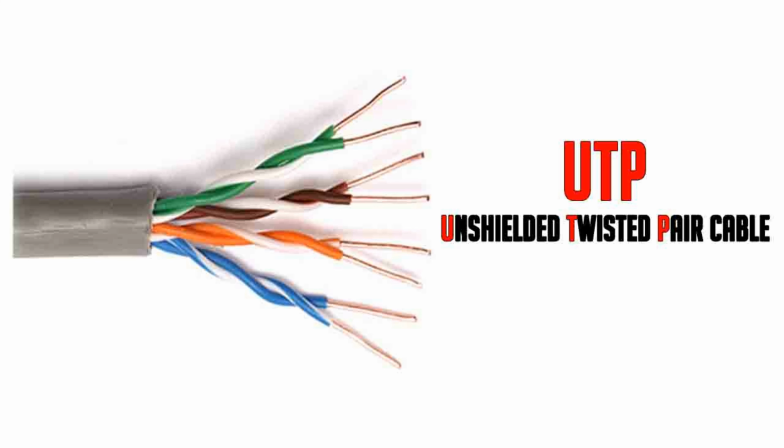The cable has 4 pairs of wires inside the jacket. Each pair is twisted with a different number of twists per inch to help eliminate interference from adjacent pairs and other electrical devices. The tighter the twisting, the higher the supported transmission rate and the greater the cost per foot.